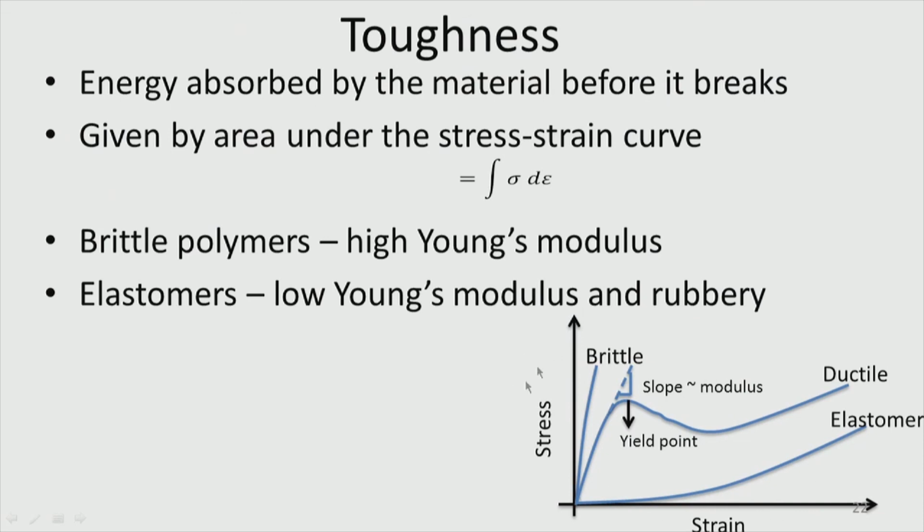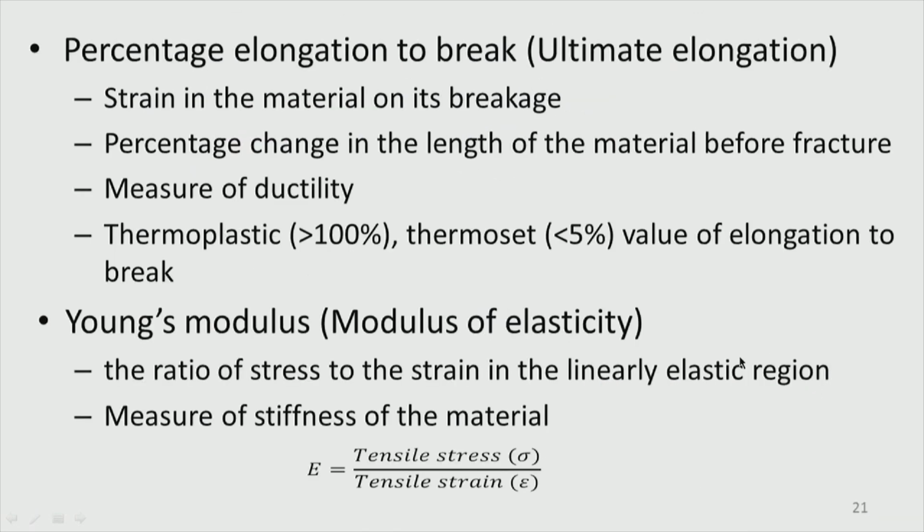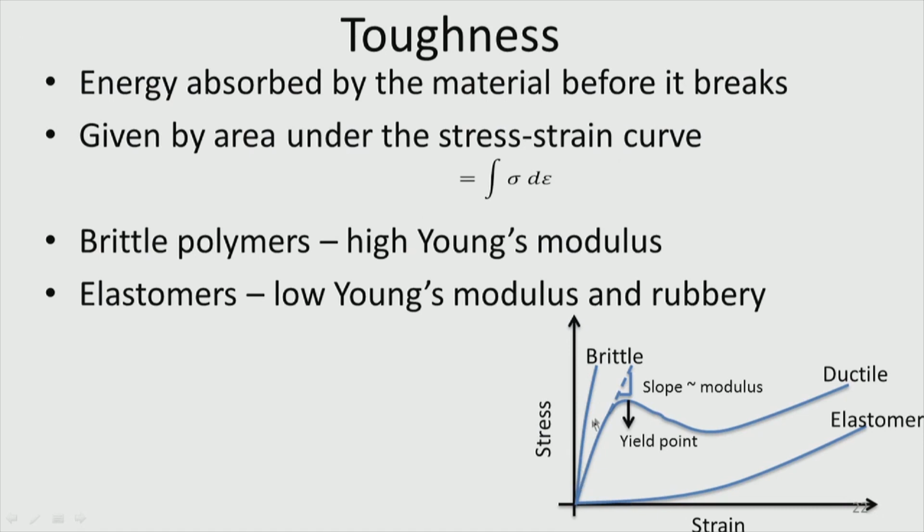This is a stress strain diagram. The slope in the elastic region, as you know, is called the Young's modulus. You remember all these, right, from a long time back. The area under the curve gives you an idea about the toughness. So for these elastomers, the brittle material, the ductile material, that is toughness, before it breaks, from the elastic to the plastic region.